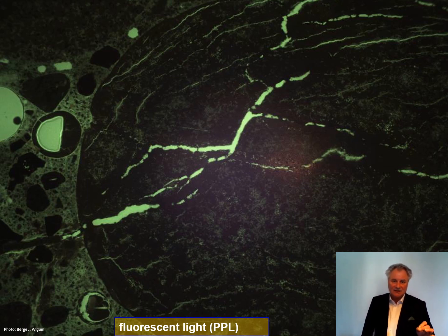And those very, very tiny cracks in reactive particles are partly filled with gel. And when this gel starts to absorb moisture, it starts to swell. And it's that swelling mechanism that makes the expansion.